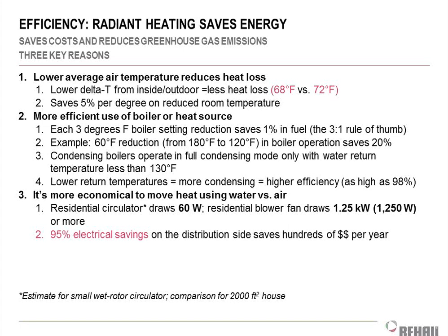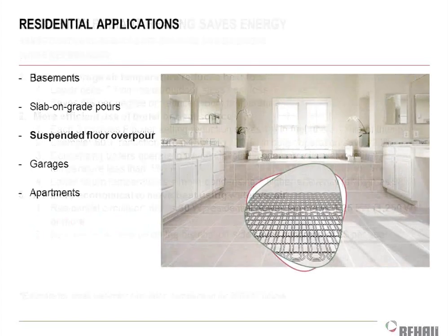Running a circulating pump is less energy consumption than running a fan, right? Air is a horrible heat transfer media. We use it for many reasons, and we almost kind of have to use it on the cooling side for dehumidification. But on the heating side, we're not locked into air, and using water-based heating systems and running a pump is a better heat transfer mechanism because water, for a given volume, can move more energy than air, right? So that's kind of the reason there. So we pretty much take whatever you're spending now to run a blower and take it down to nearly zero to run a pump. I'm not going to say zero because that's obviously not true, but close. Big, huge reduction there.